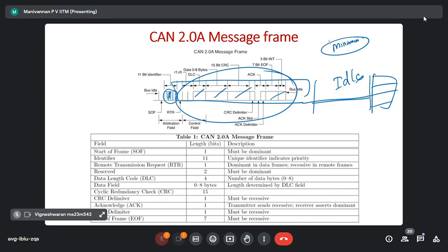There will be that overlapping, right? 100 microseconds. It can be. Why I tell you? You are transmitting 64-bit data. Correct? Here the longest you are transmitting is 64-bit data. This is a 15-bit CRC. This is 11 bits, all these things.